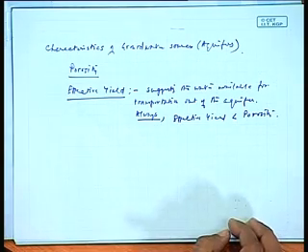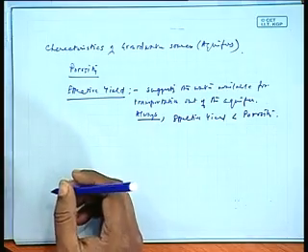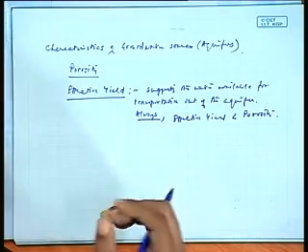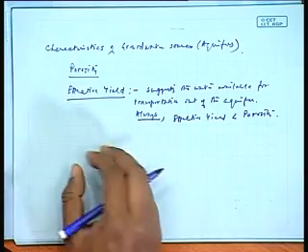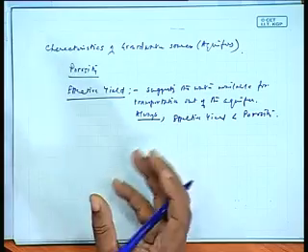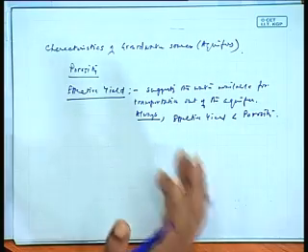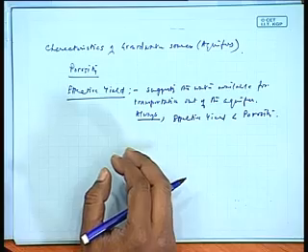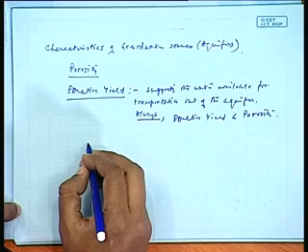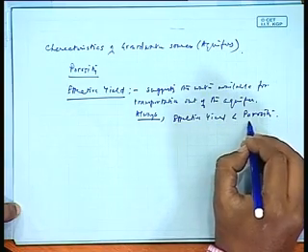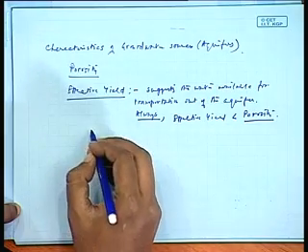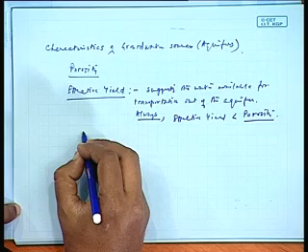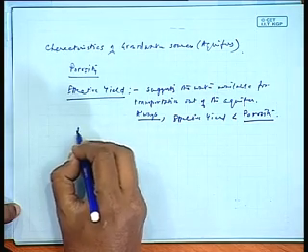The same example I have given for soil can also be given for any other geological structures. Even if the contained water may be 30%, whatever is available for transportation may be only 20% of the volume. So you can see that the porosity would always be more than the effective yield, or the effective yield would be less than the porosity. In such cases, let us have a brief idea about the representative values.